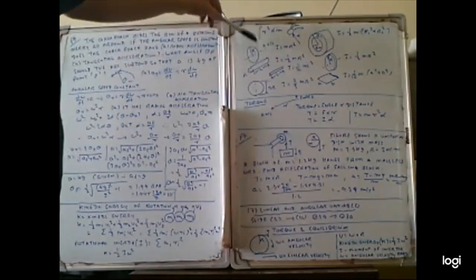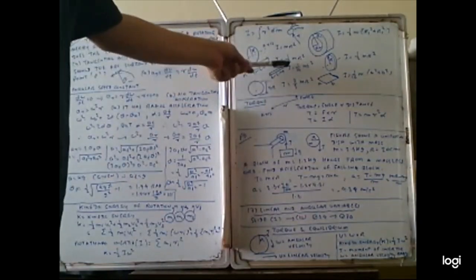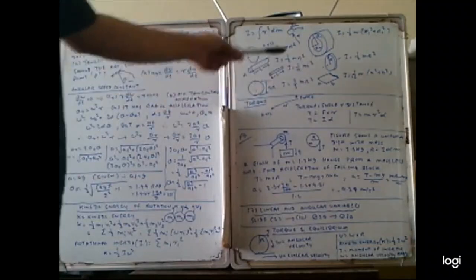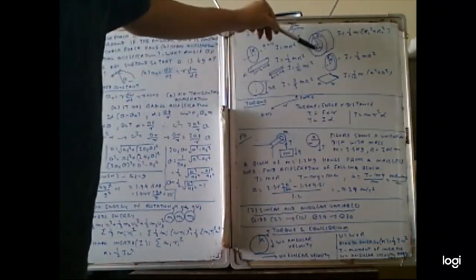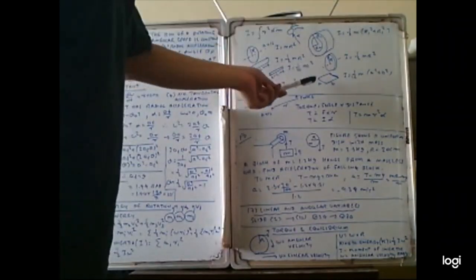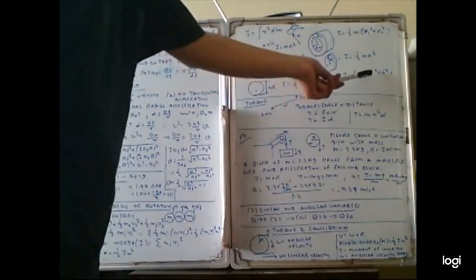So those equations are for this bracket R. Moment of inertia is I equals M R square, where M is the mass. And this one, this is the rod of length L, so I equals 1 by 12 M L square. And this one has internal radius R2 and external radius R1. In this case, I equals half M (R1 square plus R2 square). And this is the straight one, with distances A and B, so that I equals half M (A square plus B square).